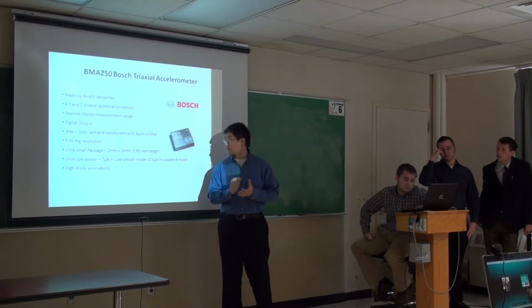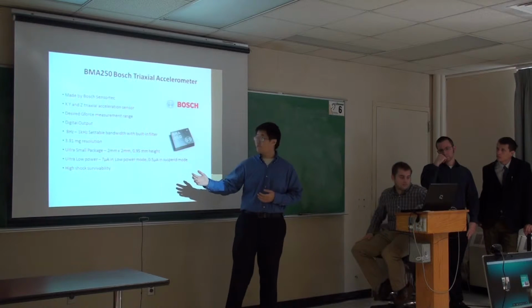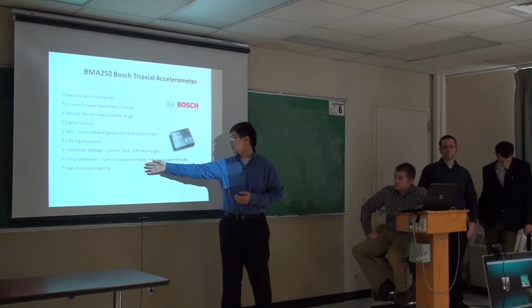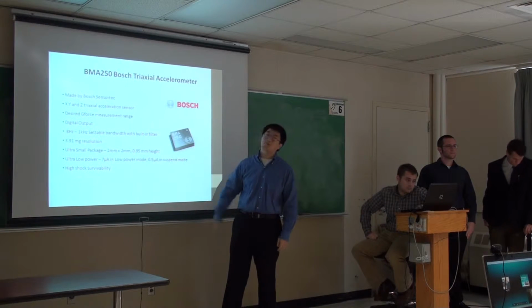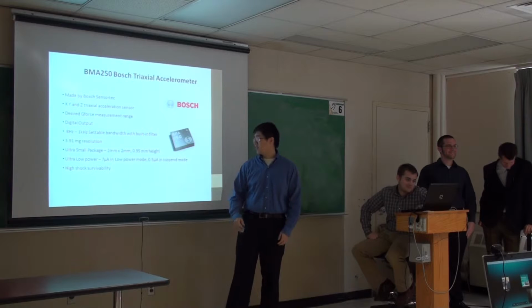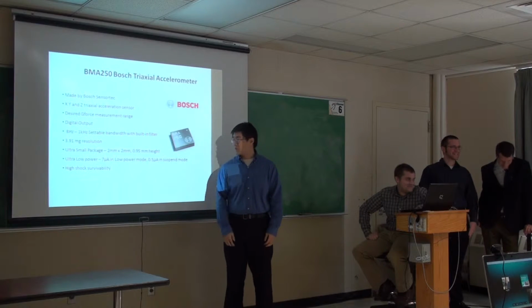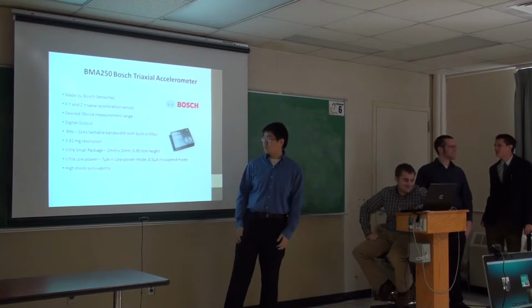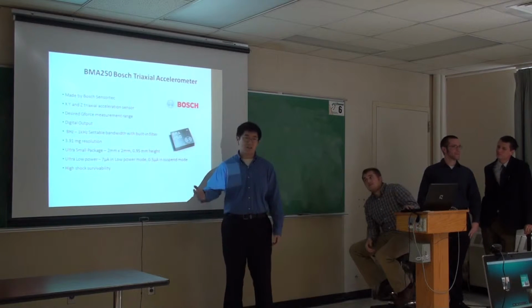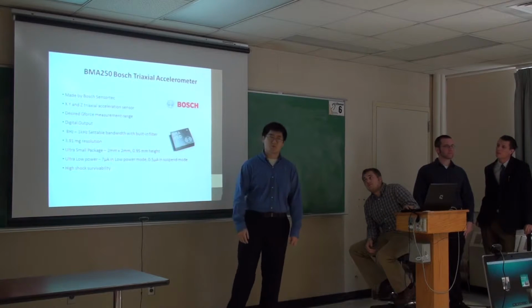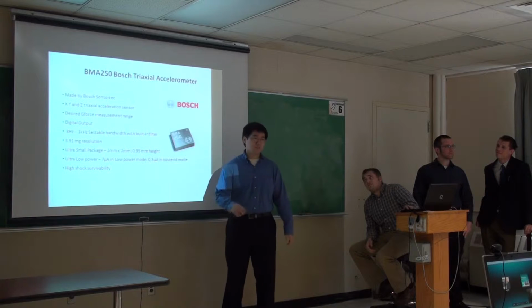One of the requirements that Tom said is that we need to have a lot of battery life. This actually runs at 0.5 microamps in suspended mode and 7 microamps in low power mode, which is exactly what we need. And lastly, it has high shock survivability, because you don't want this to break when we're actually measuring the acceleration.